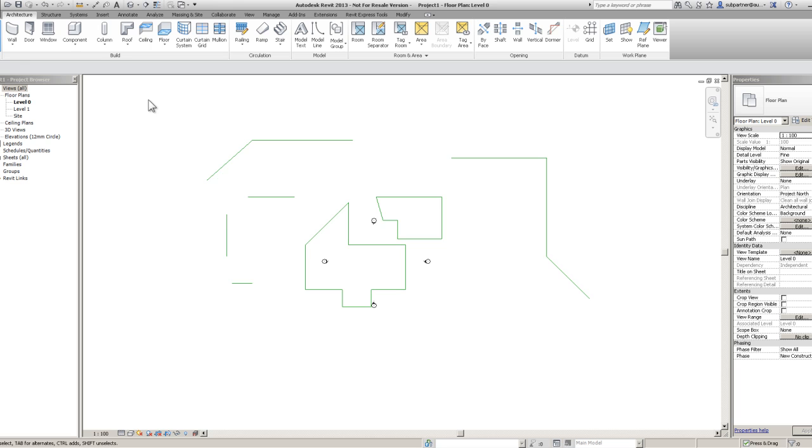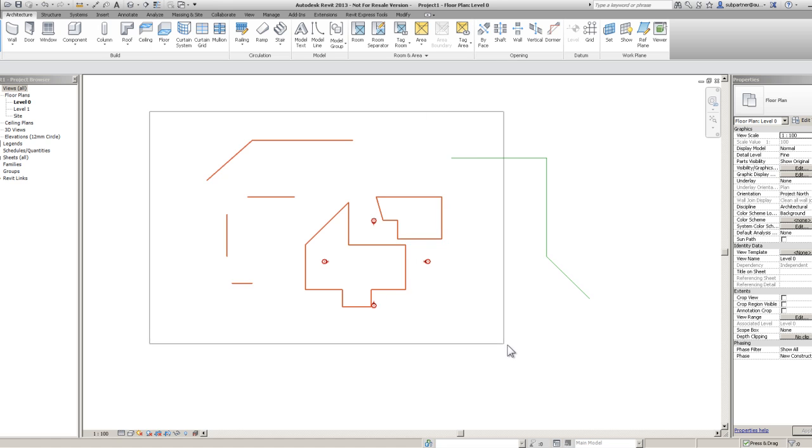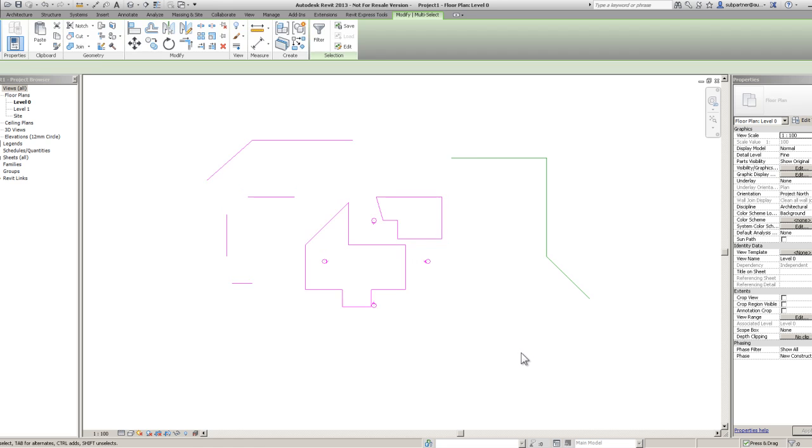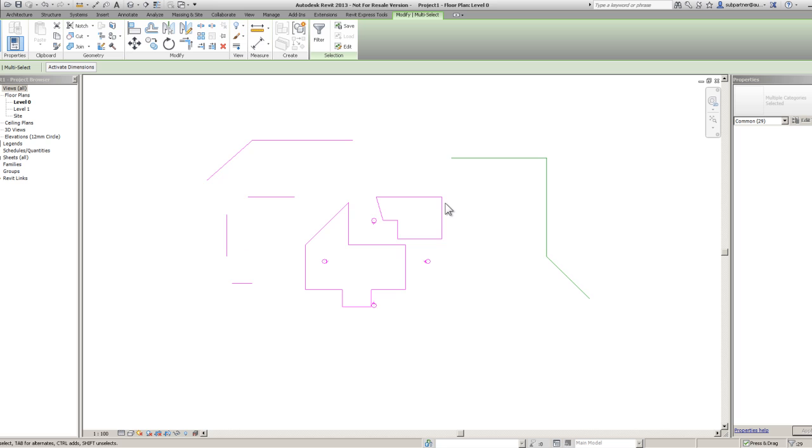If we move our mouse over to the left, and this time instead of left clicking, we left click and hold, and just start to move my mouse down to the right. I'm going to move it slowly. It works exactly the same as AutoCAD. You can see, just there, it will only select, or in this case soft select at first, something that I am completely covering. Keep going, and you can see how that's working. I'm just going to drop it to there, like so. You see how it selected these objects because the window completely covered them.